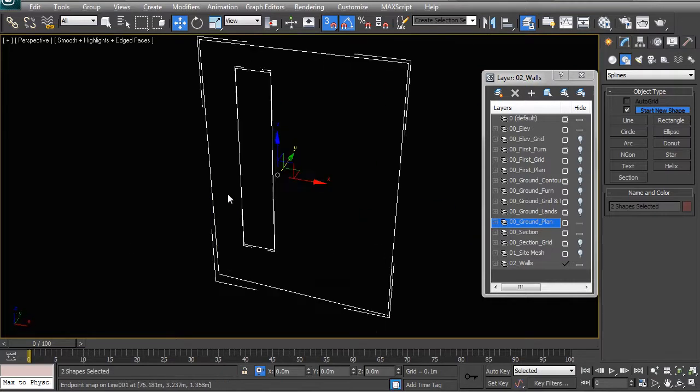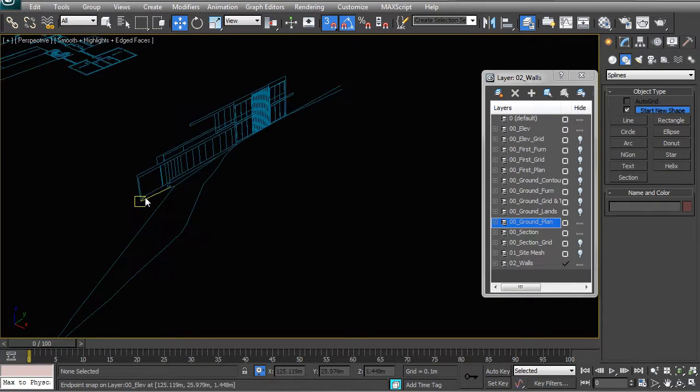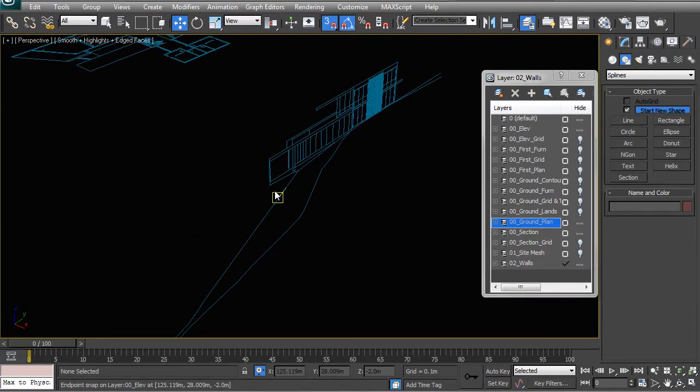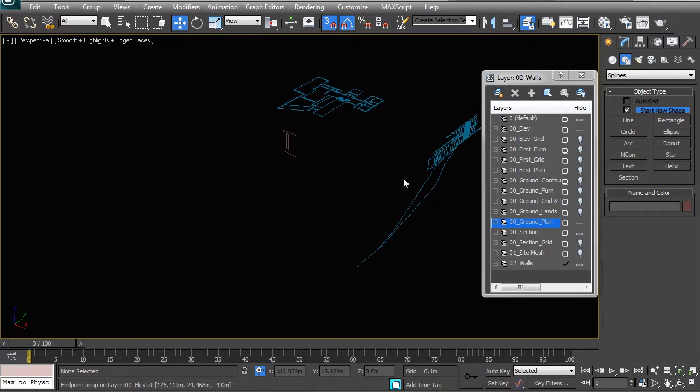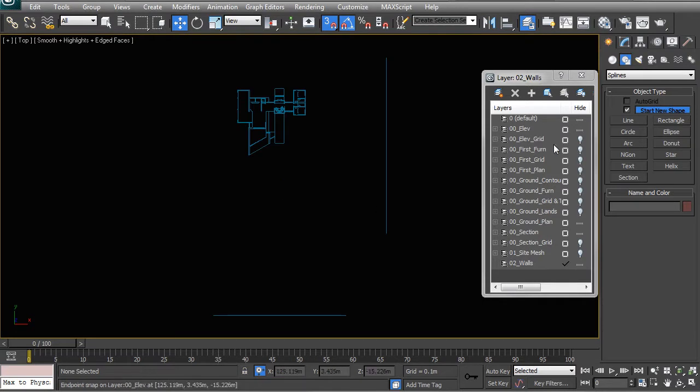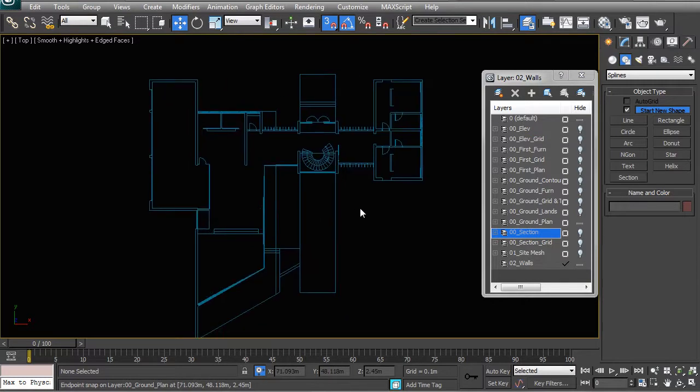but you will run into many hassles because there are a whole lot of constraints with this method. Namely, your elevations don't always reveal all the walls that you need to model. Second of all, we don't even have all the elevations, and this one is actually a section, so there's a lot of information missing to use this type of method, which is elevational in origin. So what we're going to do is leave that alone and focus on the plan. I'm going to turn off my elevation and section straight away, since I'm not going to be looking at them now, and let's have a look at the plan and the different methods that we can use to draw walls off the plan.